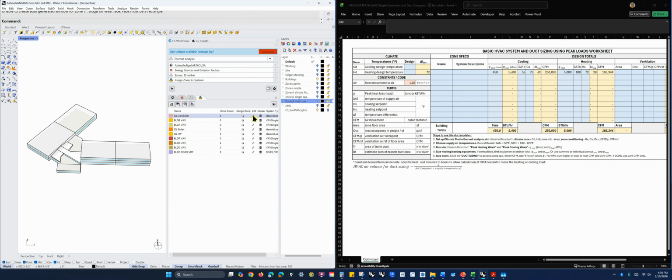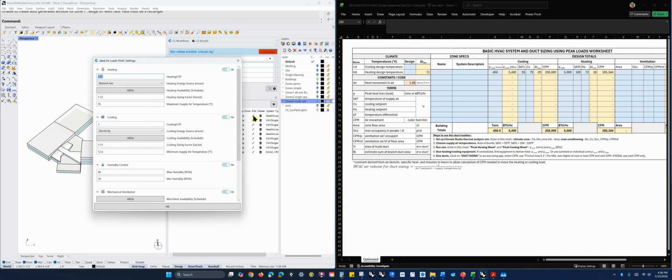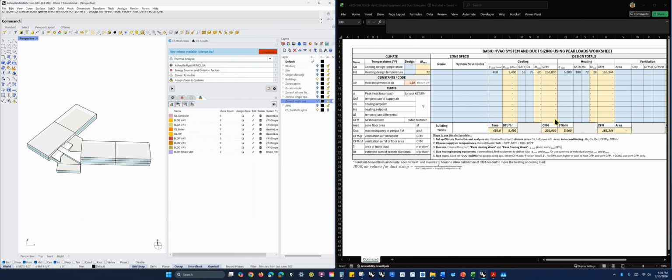I think the default when you run these simulations is 95 degrees for the maximum supply air temperature and 53.6 for the cooling supply. So maybe I should use those, since that's what the simulation was run on. But again, 53.6 is kind of little. But let's just do it, 50. And that's probably a conversion from metric. And then over here we were saying 95.